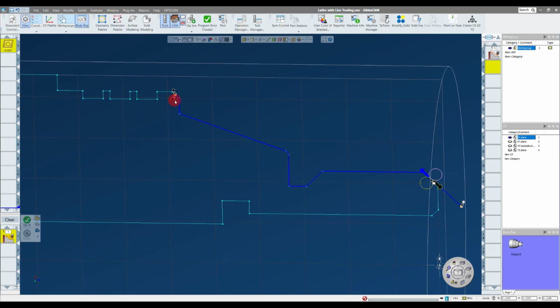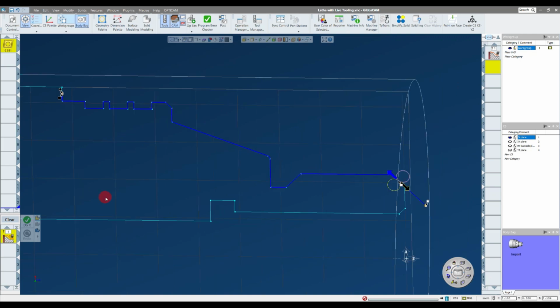But what I can also do is hold Control and Shift at the same time. I usually do it with one finger, but you can use two. If you hold Control and Shift, it turns your cursor into this little plus. And if you just click on that line, it moves your markers there as well. So, a little time-saving trick.